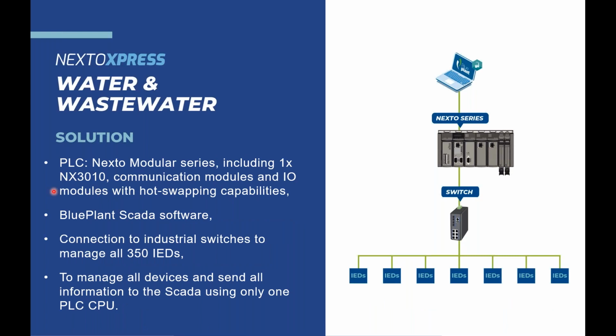So what we did: one PLC, Nexto 3010, communicating with all the modules, all the communication protocols, all the IEDs, and with hot swapping capabilities. Any of these modules, you can just plug out and plug in, and you don't lose any kind of control or information from the field.